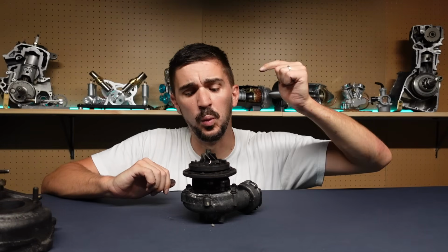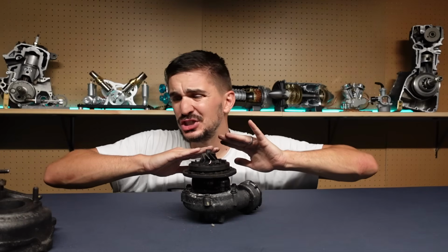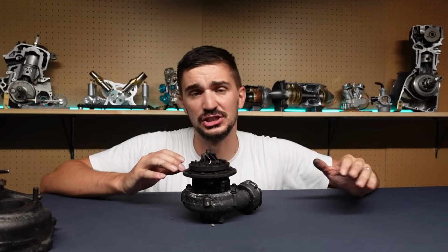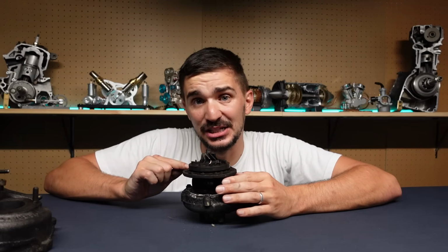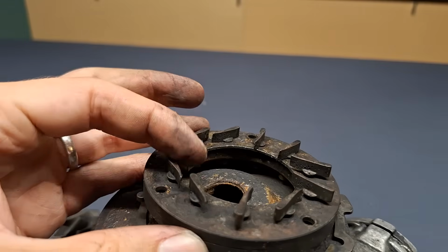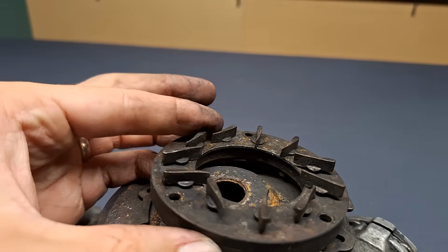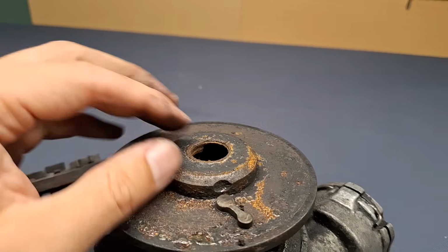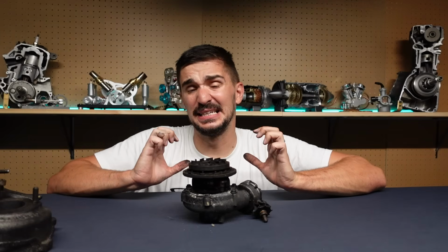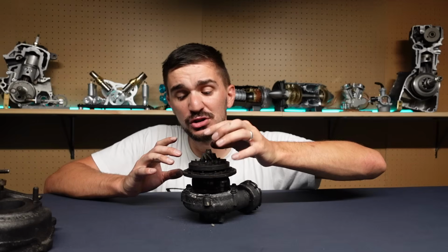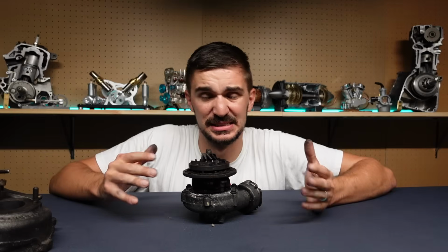So the question is then, why do we see VGT turbos pretty much exclusively on diesel applications, but almost never on gasoline applications? Well, as we know, gasoline engines have an increased exhaust gas temperature. And as you can see, this system is kind of flimsy and kind of delicate, which means that to work at increased exhaust gas temperatures, it needs some very exotic and expensive materials, which means that it is really not a cost-effective solution. So we only see it on stuff like a Porsche, and maybe someone else, which is a luxury high-performance gasoline vehicle.